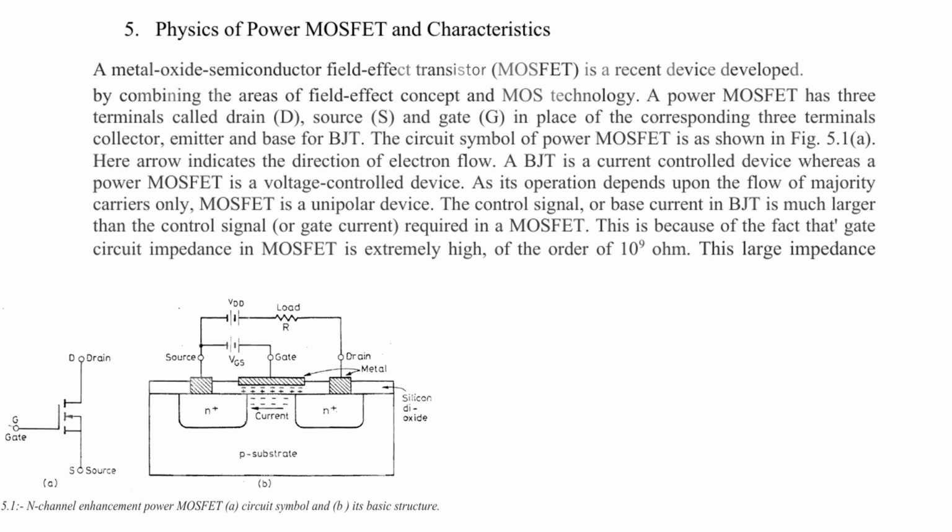If you remember, this is the N type material, a P type substrate is there, a channel in between them, and a silicon dioxide layer. By diffusion you can grow this N layer and N layer. So you can also have the gate terminal, and next to the gate terminal you will have one voltage, that is the gate voltage, and this is your VDD.